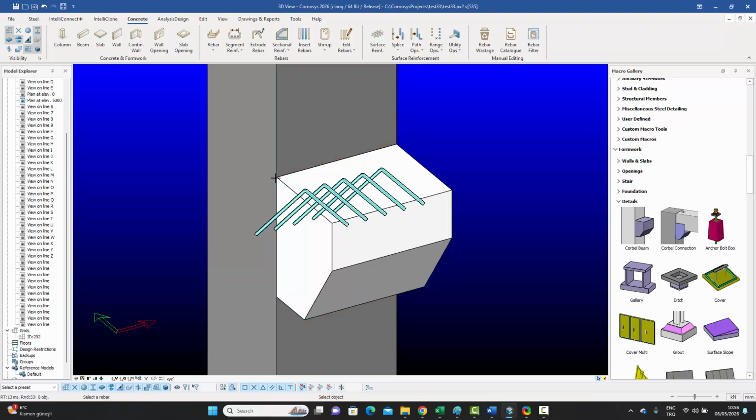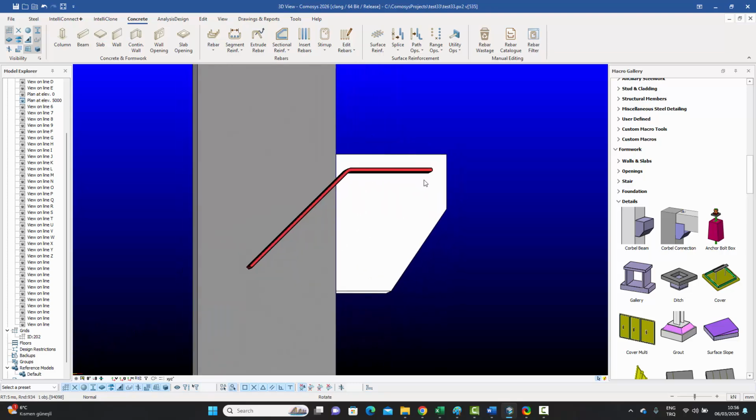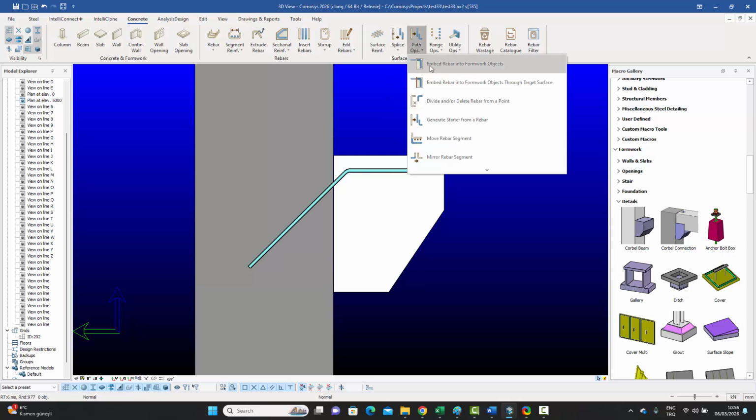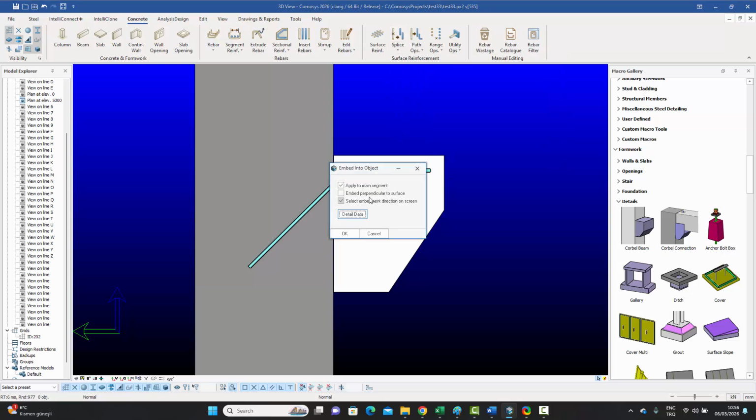If I press enter, you will see that the embedment which has been achieved now takes a direct turn of 45 degrees from that point, and this length is the required length which we wanted of 50 feet. The diameter is 10, so it should be about 500. So this option allows you to change the direction of the embedment if you turn it on. But like I said, by default, it's just going to go straight.